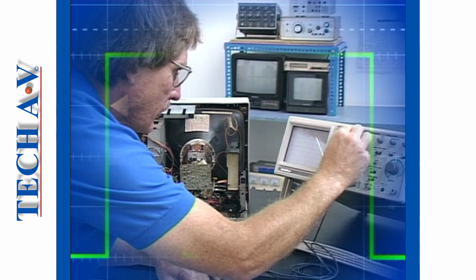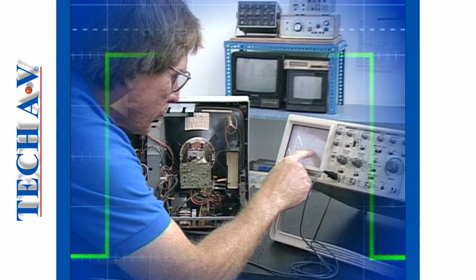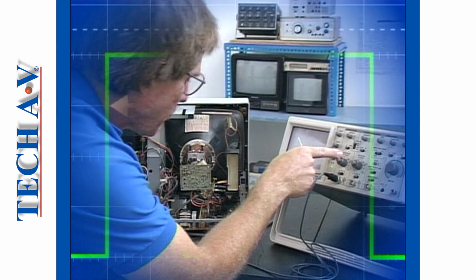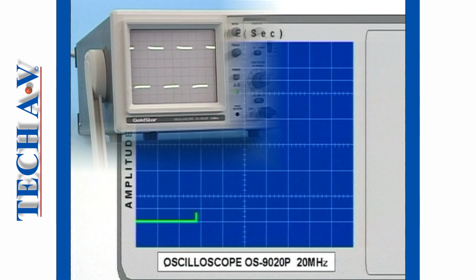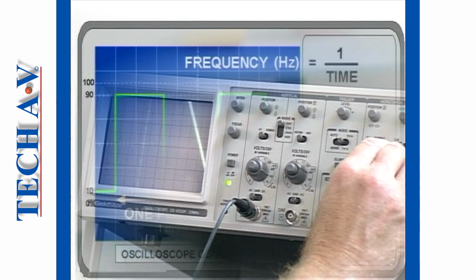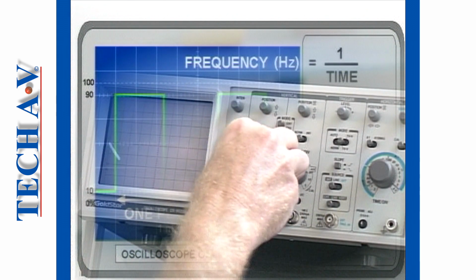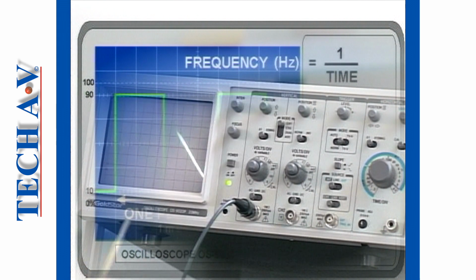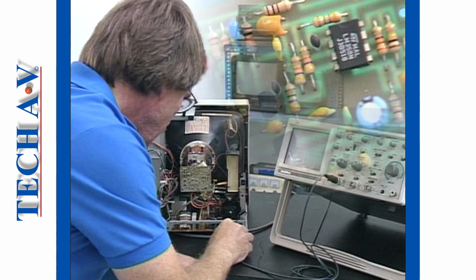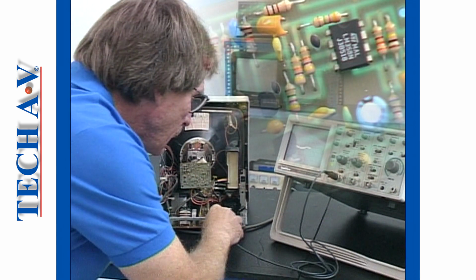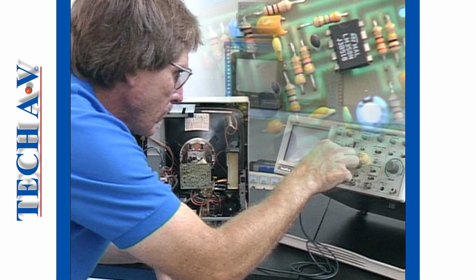Oscilloscopes are precision measuring instruments and are used extensively in the design, testing and fault finding of electrical and electronic equipment. Unlike an analog or digital multimeter, the oscilloscope, or scope as it is often called, will trace out a picture of the voltage under test by rapidly plotting the changes in voltage over a set period of time. The operator will examine the behavior of the patterns or waveforms displayed on the cathode ray screen and calculate various values relating to the signals under test.